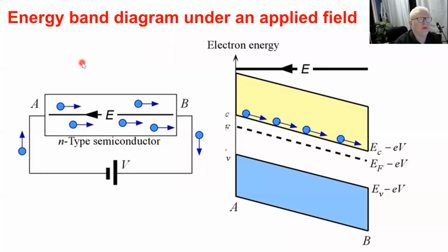Now it's part number 2 of our energy band diagram lecture, lecture number 3 in the solid state course. Okay, so this was our terminating slide by part number 1 when we studied the effect of applying an electrical field on the energy band diagram, and we understand that theory of what's called the minimum potential theory. Here, as you can see, electron will drift toward the right direction due to this positive terminal of the battery, while the holes will drift to the left direction due to the negative terminal of the battery.